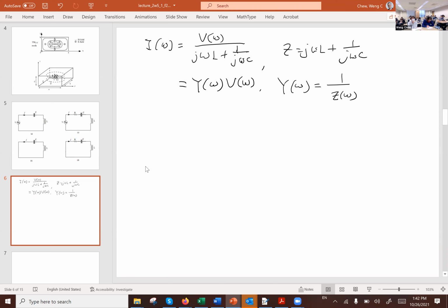Okay, so the peculiar thing about this transfer function is that there will occur a frequency at which this denominator is equal to 0, and that is the resonance frequency of the system. So we have seen this over and again, which is that when you hit the pole of a system, you hit resonance. We saw that in the Fresnel reflection coefficient. We saw that in the generalized reflection coefficient. We saw that in the transmission line theory. Okay, so this is quite easy to understand.